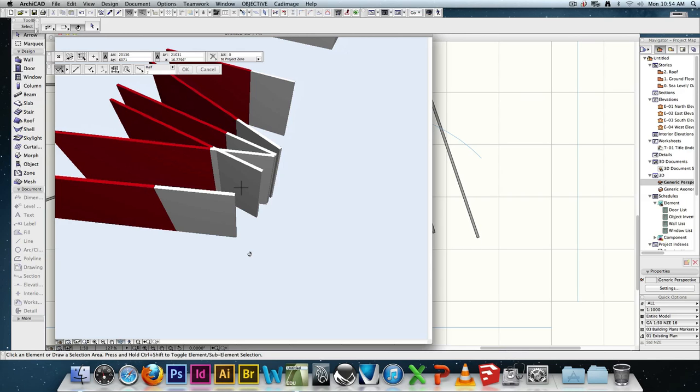Did you put the arc again to then? Yep, so select the walls first. Select the walls because walls are what you're cutting. I don't know what will happen if you've got the line. Yeah, so if you hold down the Shift key, you can unselect. There you go. Grab your X. Yep. And then click on that wall, or that line, sorry. Yep. And then which side do you want to keep selected?